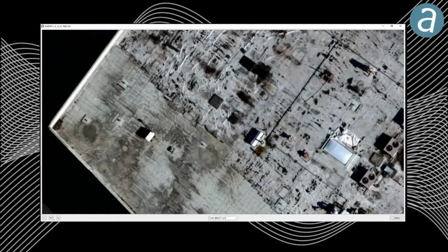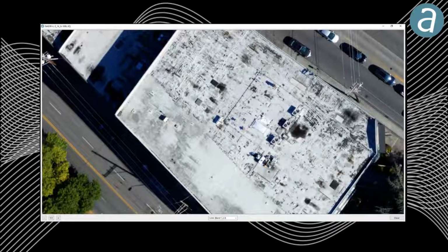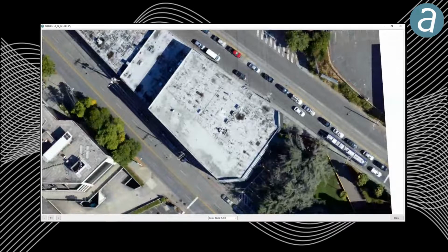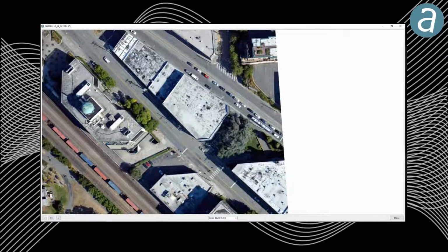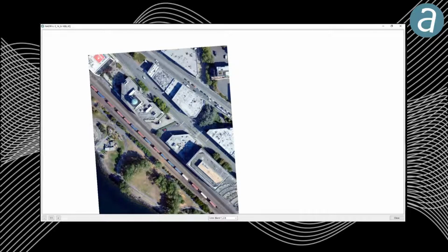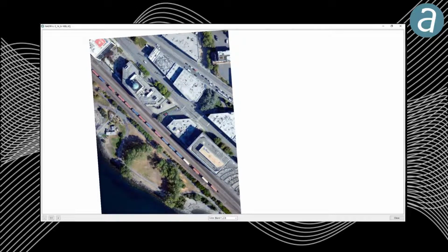And how is this useful? When you run the tie point extraction, for instance, when you try to connect the images, trying to find similar features from all the surrounding images, by using these 65,000 shades per channel, you will have way more options to attach the images and to identify similar features. So this is another advantage of using the IIQs. You guarantee that you keep all the bits per channel, the intensity you have from your images.